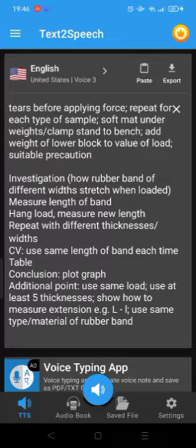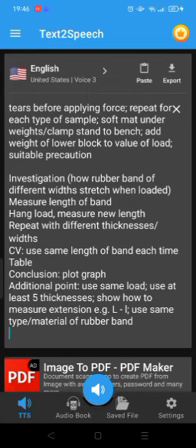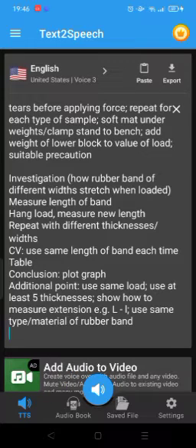Always measure from the same point on the spring, top or bottom of the ring. Wait for the spring to stop bouncing. When using a horizontal aid, ensure the rule is vertical.